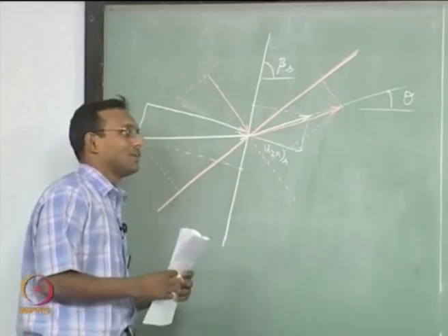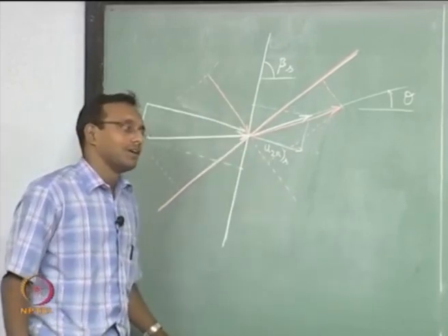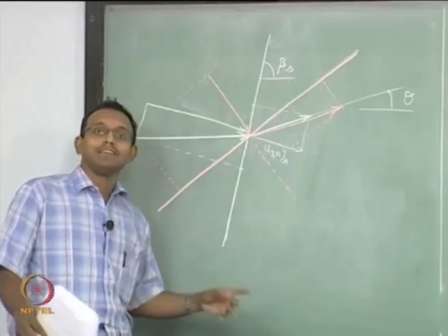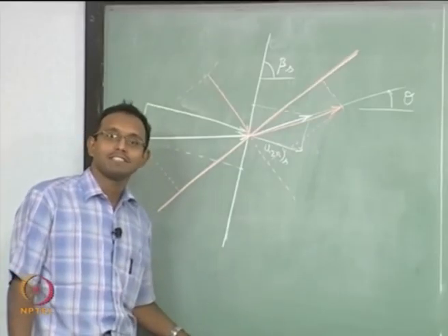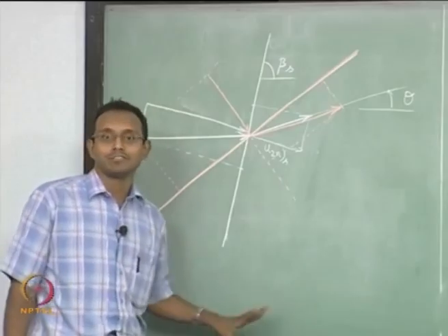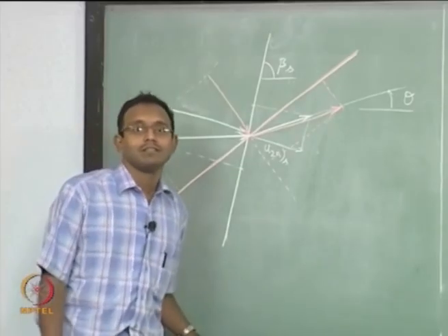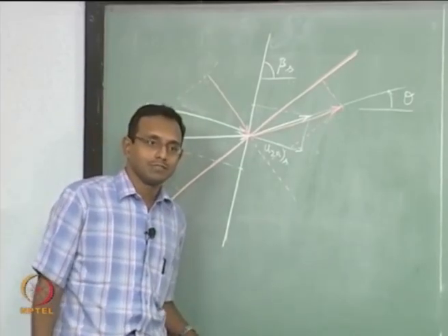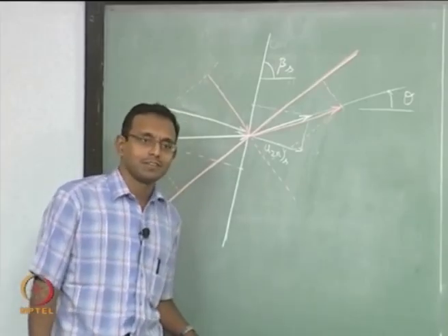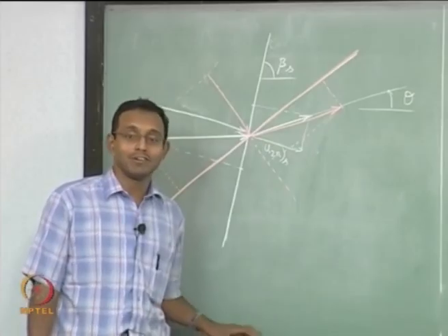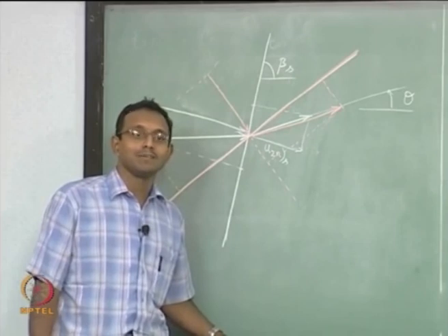Okay. Now, I will tell you one more thing. It so happens that we have two solutions, but in real life we see mostly only weak shocks. If I have a steady problem, I see only weak shocks. Okay. Till now I have not seen a steady, stable, strong shock solution. Okay. And I have not seen anywhere in literature also a stable strong shock solution. Okay. That being said, that does not mean people have not observed strong shock solutions. They have observed it, but in unsteady problems.